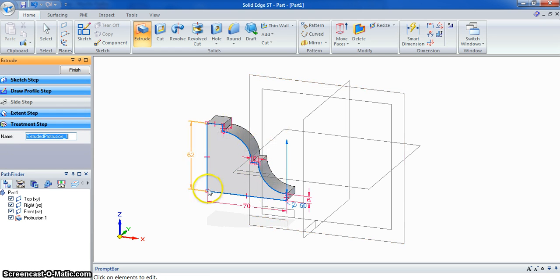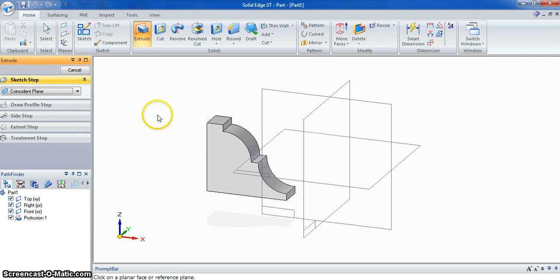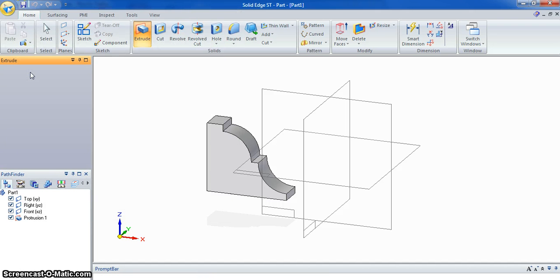I still have a blue line there. Make sure you get rid of that blue line. Otherwise, if you go to save your drawing right now and open that drawing up, you will not have the molded edge there. It has not been finished. So you have to either hit finish or right click on your screen to make sure that's finished. And then save as and save your molded edging. Well done, you're finished.